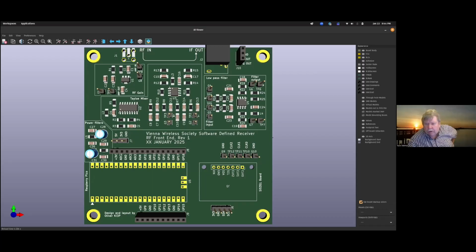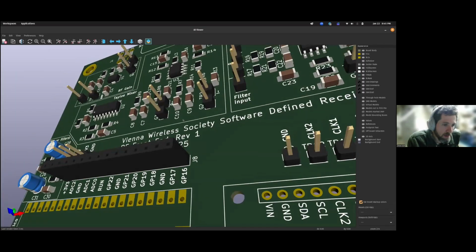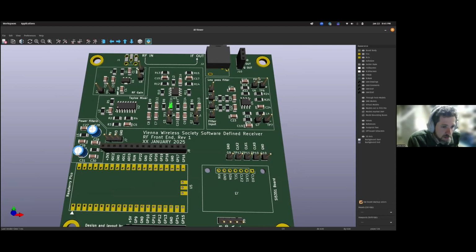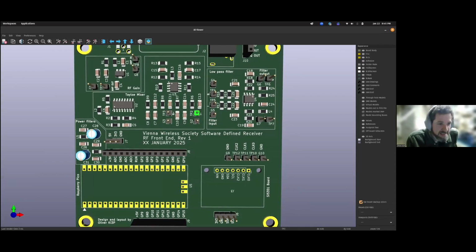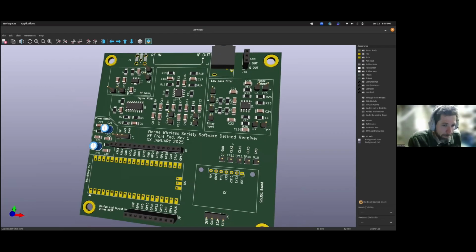Quick question, Oliver. Sure. Those capacitors and resistors, are those like 0805s or 1206s? These are 1206s. Okay, good. Thank you. Yes, we've gone for the easiest to solder. Not that it'll be easy, but the easiest to solder. And similarly, we picked these op amps and components that they have a wider pitch spacing of their pins, so they're easier to do with the hand. I prefer 1206. So they're like 1/8-inch resistor sizes. That's 1/8 watt resistor sizes for axial, pretty easy to use.